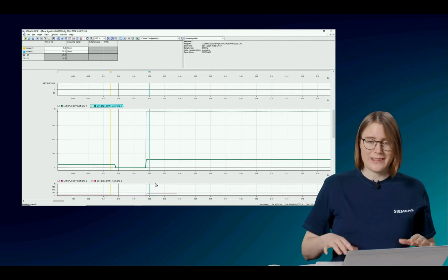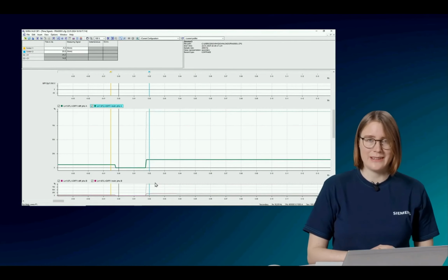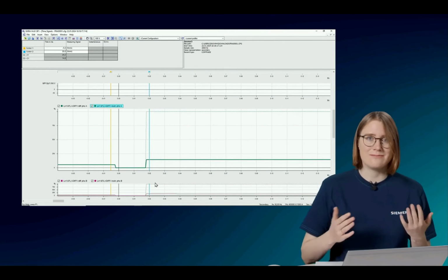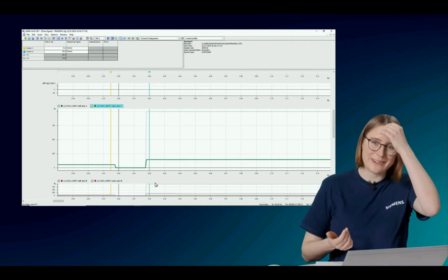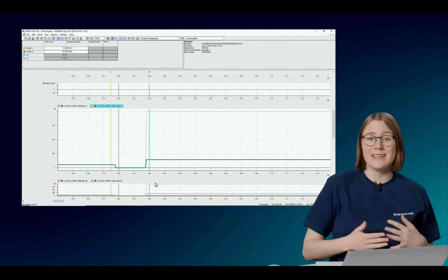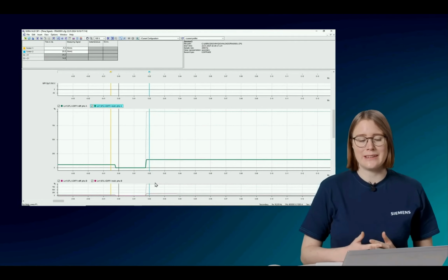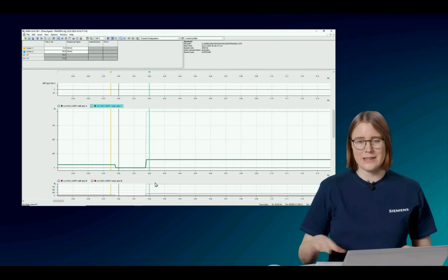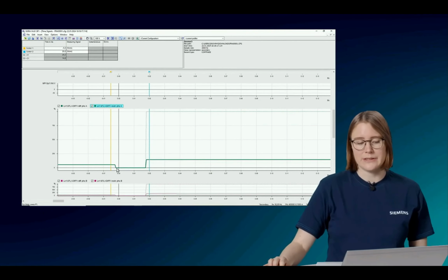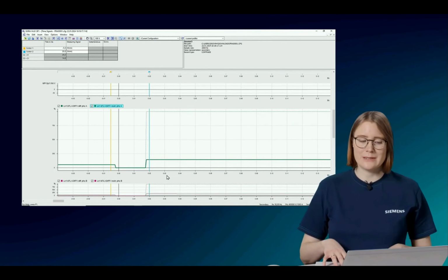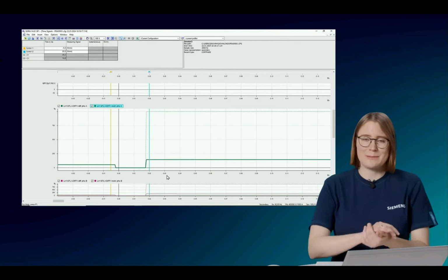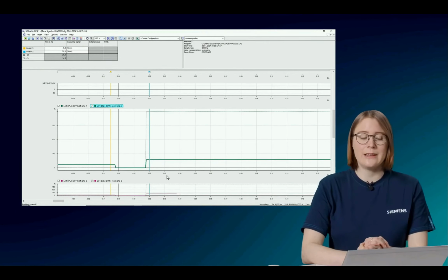But for the sensitive stage, we want to make sure, even if the fault is somewhere at the border, if it is a fault or not. We want to make sure that we have a clear measurement. Therefore, we block the sensitive stage for one time period here, for 20 milliseconds. If you want to learn more about the theory, the algorithms behind line differential protection, we will also have a session about it.